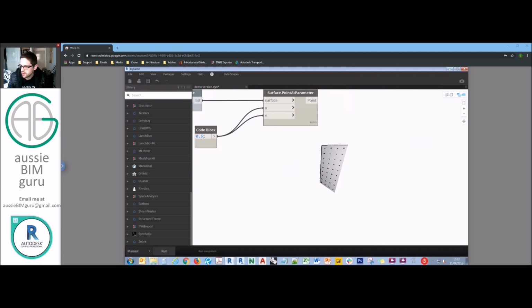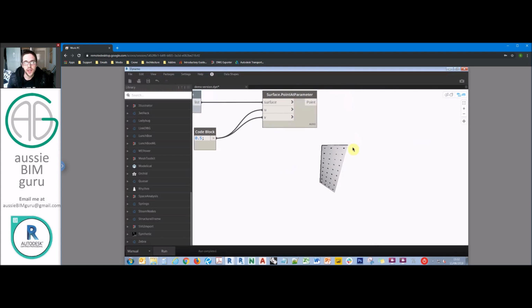So what we need to do from there is find out if it's pointing away from the face or into the face in a normal direction, because we need to offset these sensors just outside the building. If we run an intersection check with rays of the sun, for example, we also want to consider the building itself. Is the building blocking the sun from this position? So we're going to push our sensors outwards away from the face of our building in order to achieve this.